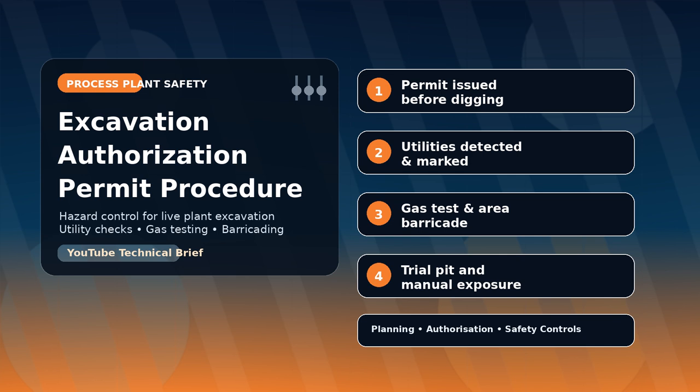As well as that, you need to have an emergency rescue plan, because if the depth is more than 4 meters and some incident happens, like a person feels dehydrated or unconscious, you cannot carry the person, and they cannot come up through the access ladder. So you may need some kind of rescue mechanism, like tripods where a winch will be there.